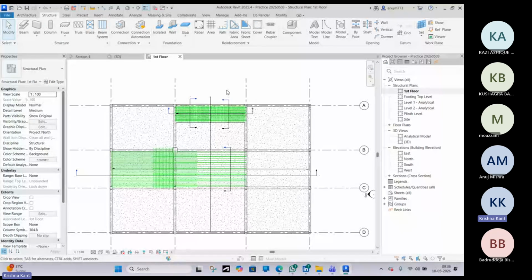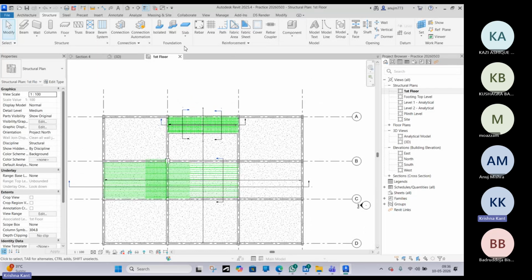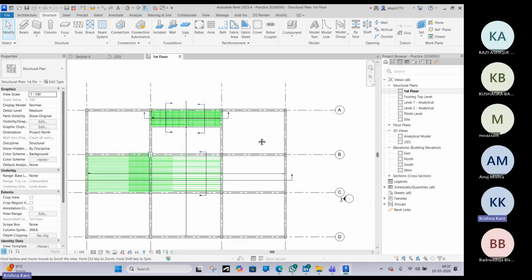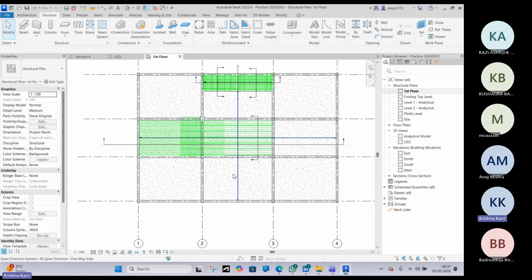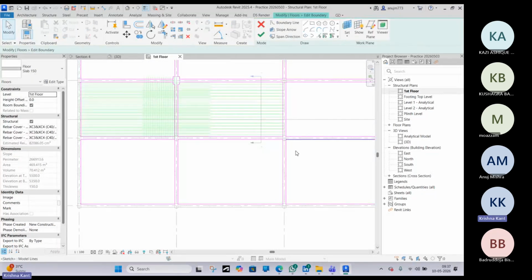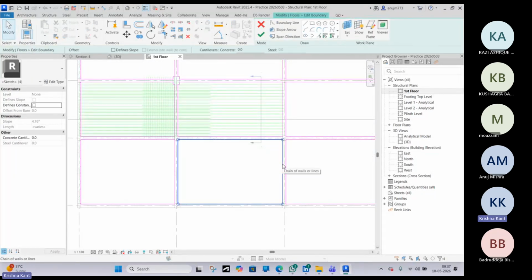So in today's session, we will have one more detail left, that is stairs. We will see the stair details, and then we will see what we are going to do with all these details, right? That is the important part. First we will create a space for stairs, so I will cut the slab in this area so that we will have stairs.